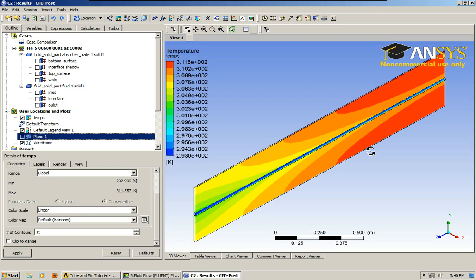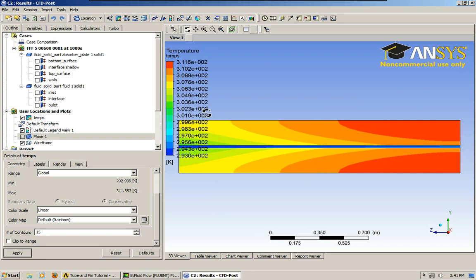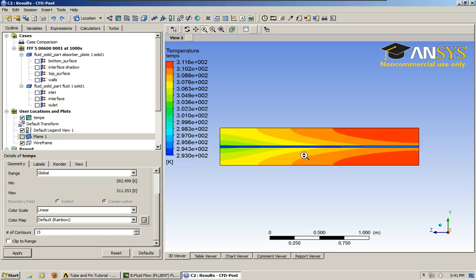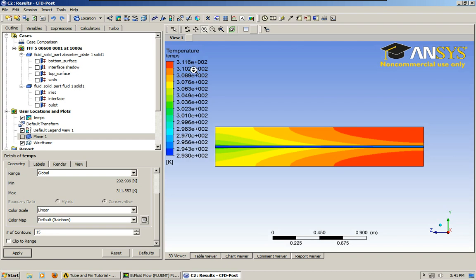Oh, another thing that I should say: whatever you see in this window is going to be what you see in the animation. So if you wanted, for instance, this view, then you've got to make sure that you select that view, put your contour in the orientation that you want it to be, select the right gradients, I guess, what do they call these?